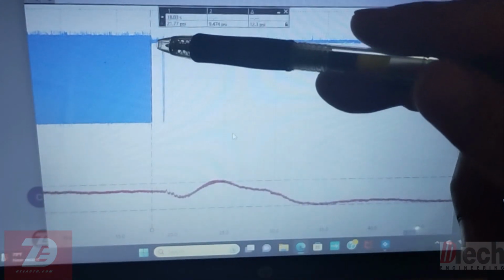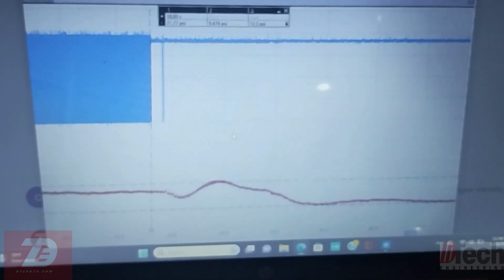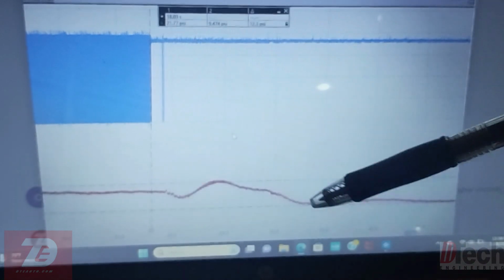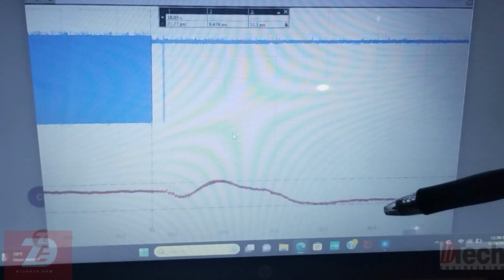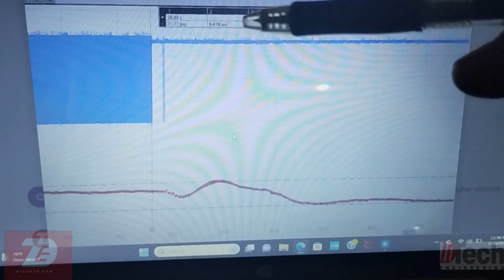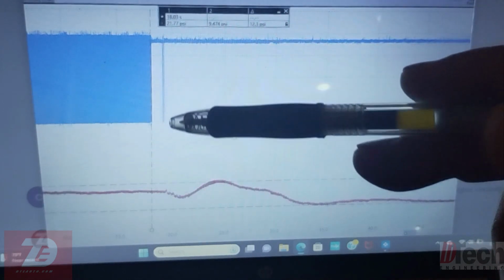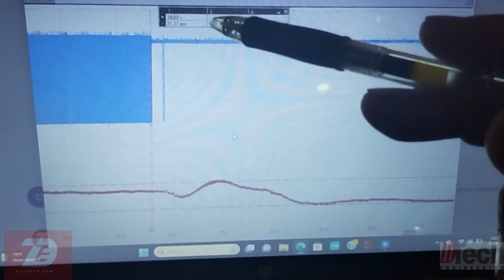When that occurred, you can see that something happened with our oil pressure level. It went from being constant to having some, I'm going to say, erratic level changes. Not too drastic, but there were some changes going on. What ended up happening here, and this can be misconstrued as a faulty DME.